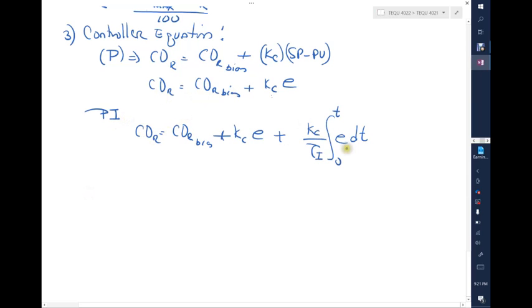You know, this is proportional, but this is a proportional integral. And this part here, Kc over tau e, is a constant, but now we have this part here, which is the integral part. So what we are saying is that this part here is the proportional part, and all this is the value for the integral part. So that's what we call a PI.